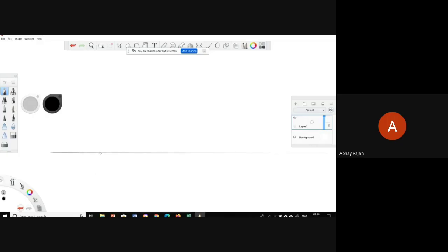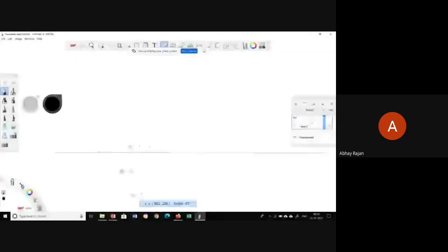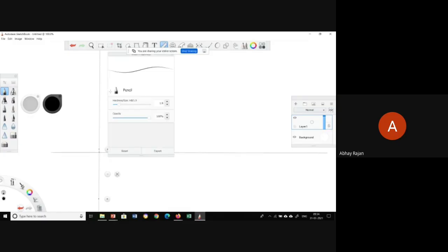I drew it a little like this so that you can understand. That's your A dash point, and then we have to take 20 mm in front of VP, right? So let me take 20 mm. Keeping your ruler here, you will be able to draw. Take a distance of 20 mm. With your ruler, you will be able to take this length as 20 mm.